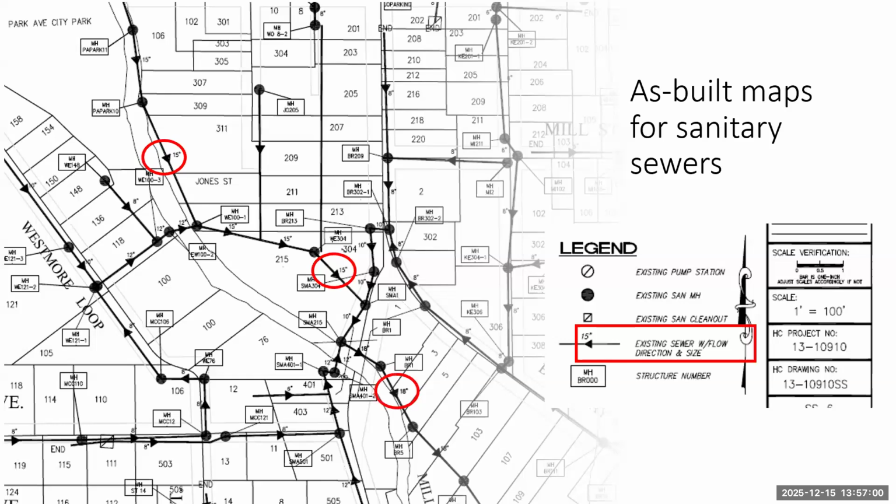So that is tracing through. Also, locations of manholes are and the name of the manhole is identified. Those are good points potentially to monitor the flows. Also, there's a structure number where you can actually, it's a good idea to have each manhole labeled so you can identify your sections of main from manhole 1 to manhole 2, for example.